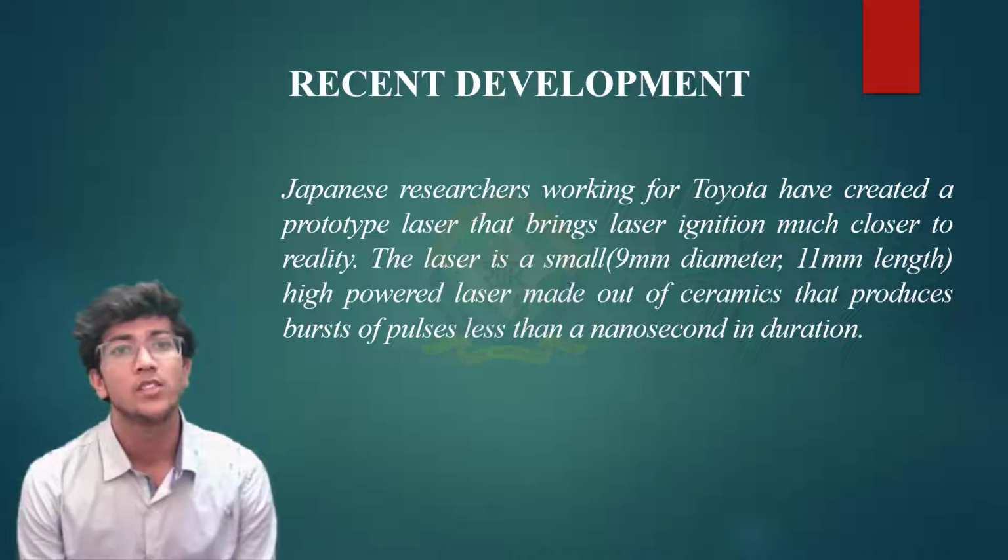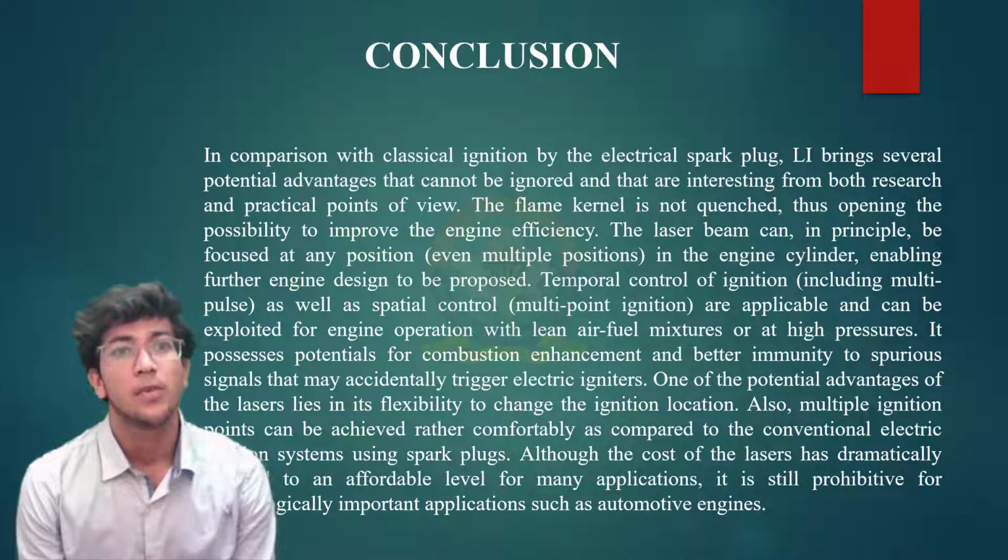So the conclusion on the laser ignition system is that, in comparison with classical ignition by the electrical spark plug, laser ignition brings several potential advantages that cannot be ignored and that are interesting from both research and practical points of view. The flame kernel is not quenched, thus opening the possibility to improve the engine efficiency. The laser beam can in principle be focused at any position in the engine cylinder, enabling further engine design to be proposed. Temporal control of ignition as well as spatial control are applicable and can be exploited for engine operation with lean fuel mixtures at high pressures.